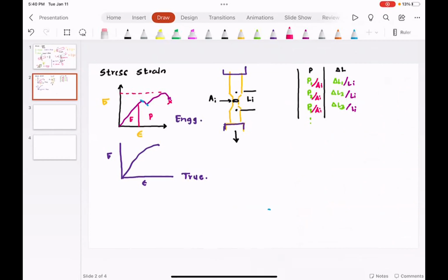So as designers, as engineers, we do not want to go into the plastic region. We always want to be in the elastic region. But recognize, in the elastic region, we don't want to be at the boundary. You don't want to sit in a car that buckles. It's safe, it has not failed, but it has buckled. You will not feel comfortable riding that car. So basically what we do is we try to be at a level which is somewhere over here.